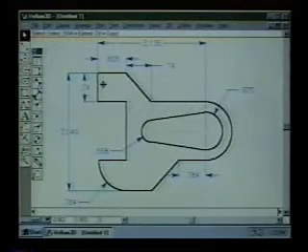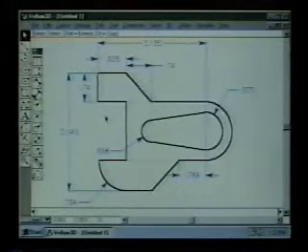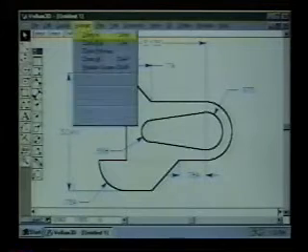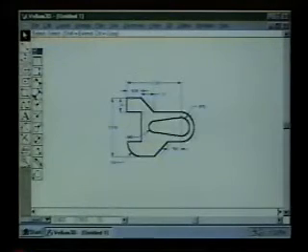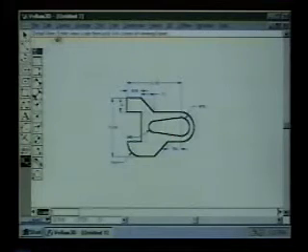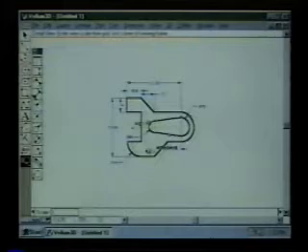And then one of the final things to let you see is that I can go in and do detailing on some of this geometry as well. Say I want to do some tight little geometry changes here, but they're too small to make out clearly. In normal drafting, what you do is you break this area out. So I'm going to zoom out one time and use my little camera tool. This is actually the detail view tool. And I can specify a view scale, it says up here. So I'm going to go down here and put a view scale of 3. And then I'm going to give it a viewing frame of this area right here.